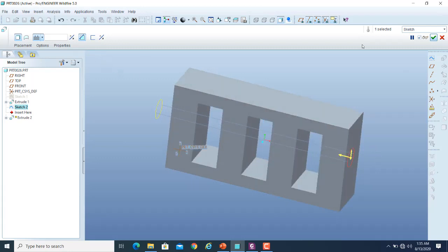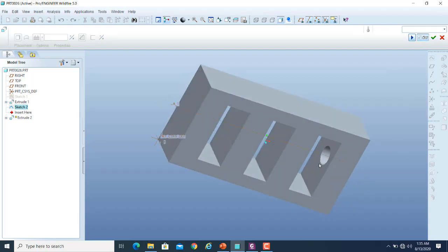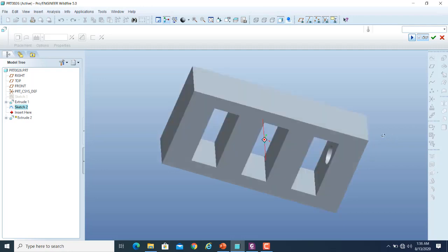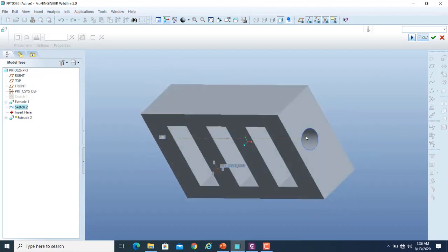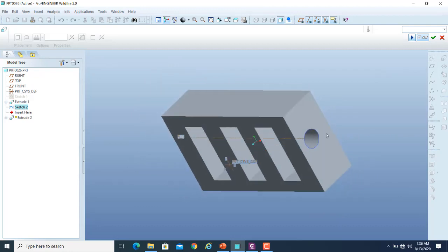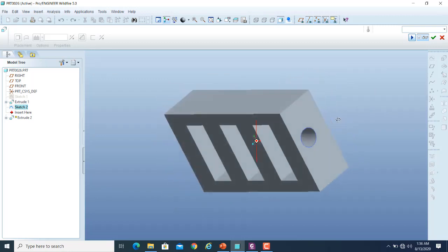So if you view it, okay, the generation will be only up to the opposite face. So this is the first face option. The first available surface will always be the opposite surface or plane of that particular region upon which you have that particular feature, whether it is a hole feature or an extruded feature.